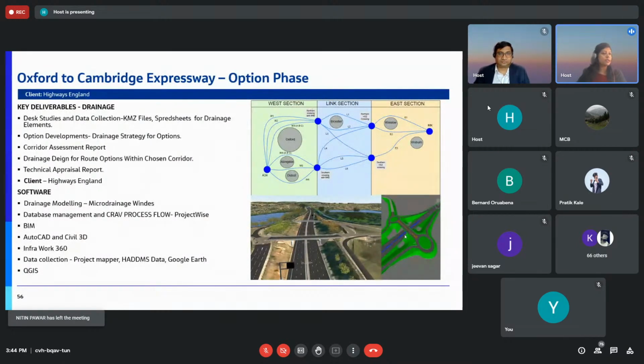What Saurav was mentioning, this shows that the road is passing under and your junction is on the top. These are the kinds of processes that you can do when you have a BIM compliant model and all your models are put together into a platform for you to check clashes and understand where there are issues, if at all there are. All of this is done at the design stage, so you don't have to reach the construction phase to have surprises and find something that is not supposed to be.